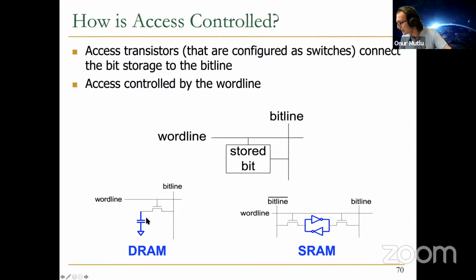So there's one question about why would you use memory to perform logic if memory is so energy and time intensive? Well, that's a good question. I think it's already partially answered, because with FPGAs, you want it to be programmable. But also smaller amounts of memory may not be as intensive, right? If you do lookup tables in huge gigabytes, maybe that's going to be energy intensive.